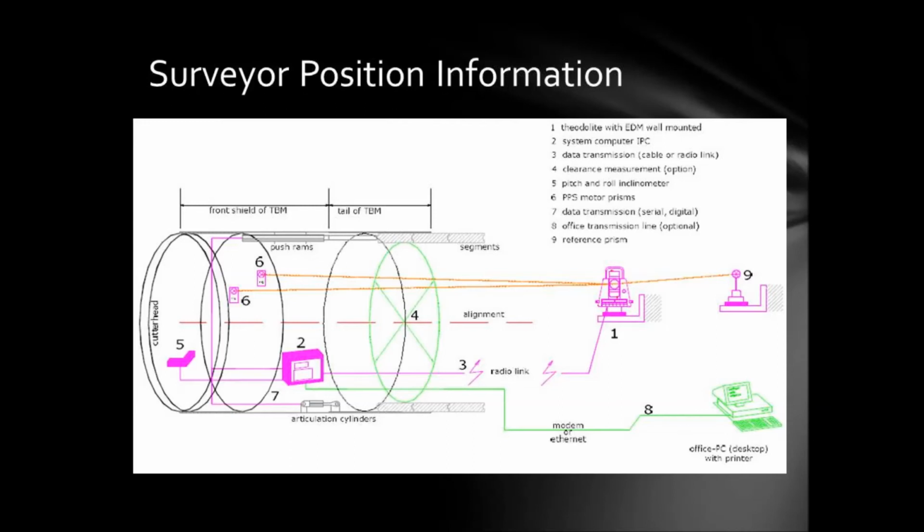It was assumed that with the surveying occurring from the back of the TBM, the coordinate system used in the kinematic model needed to also be located at the back, in the center of the rear shield. For developing a controllable design, a coordinate reference frame could also be placed at the front of the TBM to incorporate the joint velocities of the articulating cylinders into another kinematic model centered around the front of the TBM.